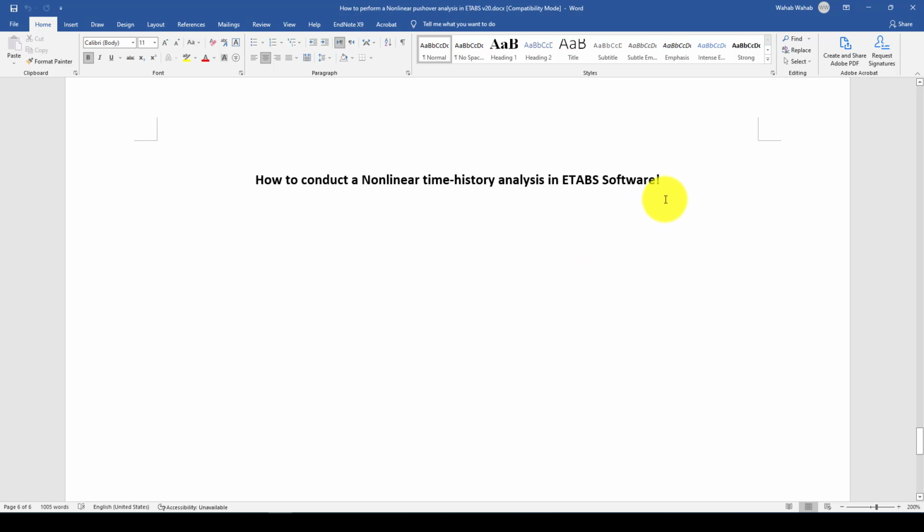There are three procedures to conduct the nonlinear time history analysis. The first one we can call the nonlinear or lumped model. It's better because we concentrate the nonlinear behavior at the ends of the beam-column elements, which can be defined as fiber elements, or as hinges, or nonlinear hinges. The second one is where the entire beam-column is fiber, and the third is a combined hinge and fiber element approach. It depends on the complexity of the model.